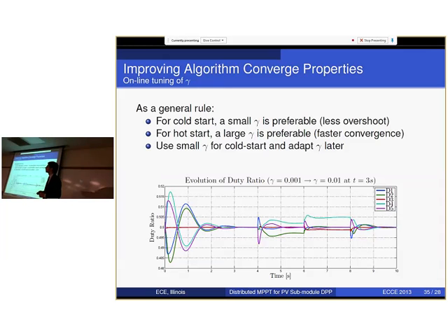Like the gamma is causing the big overshoot, but also the fact that you're estimating the derivative, right? Mm-hmm. And you have different information now, so you're not getting direct information from that communication link that failed, right? So now your estimate of the derivative is large, which is amplified by your gamma. So I think that's the reason it happens with communication failure, right? Yes. Yeah. Thank you.